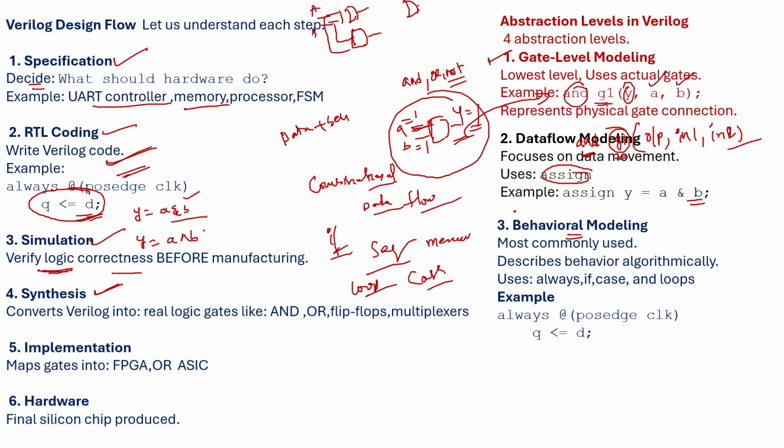Another half adder, that is another XOR gate, is connected to the output side, and another AND gate. This output is connected to this one, and another C input we give here is connected here, and then we get the carry output here. All these things are implemented using gate level modeling.